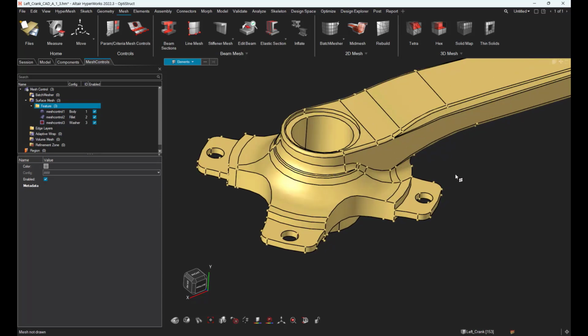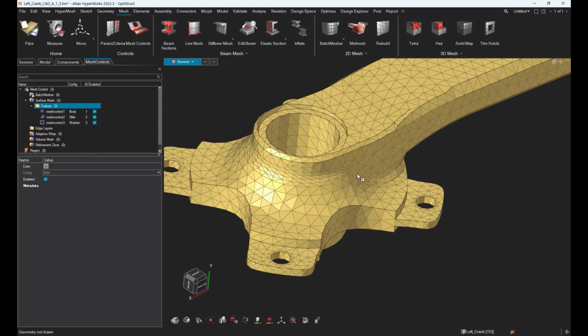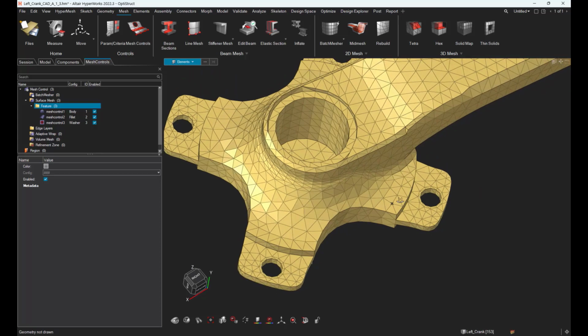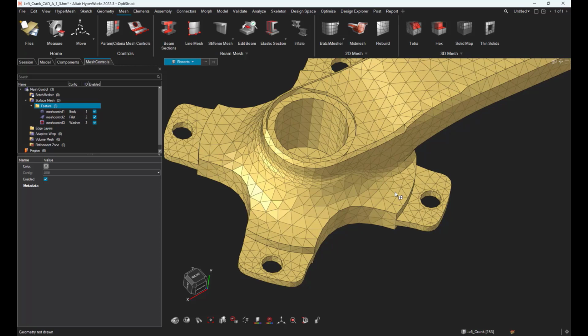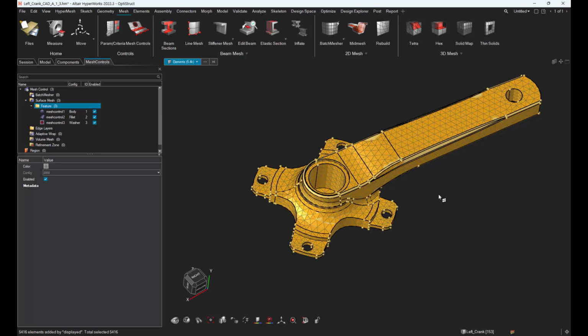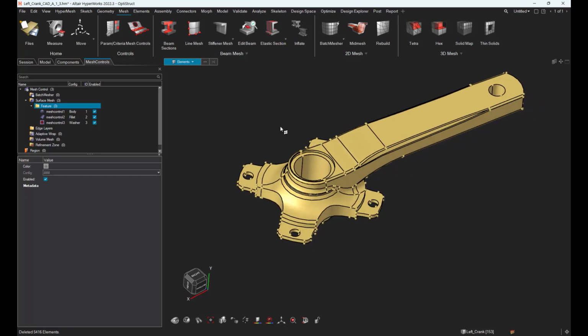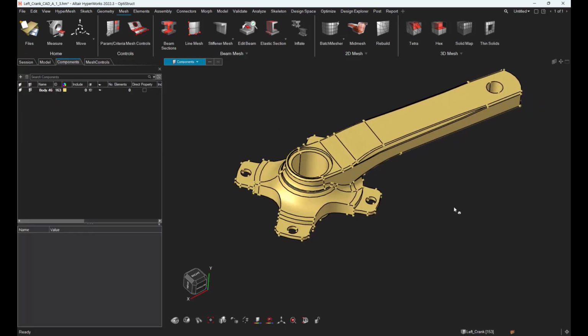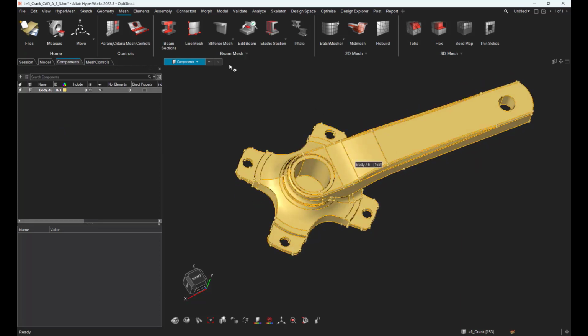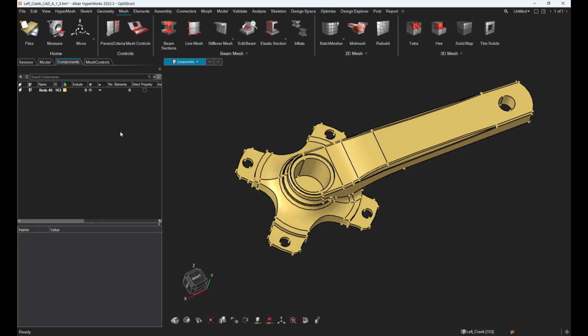Okay. As you could see, automatically we could get this kind of nice mesh pattern on the fillet, this kind of washer, without doing any geometry cleanup or modification, directly on the mesh. Okay, let me delete every element and let me talk about one specific topic. What if you would like to have a conformal mesh between 2 components?